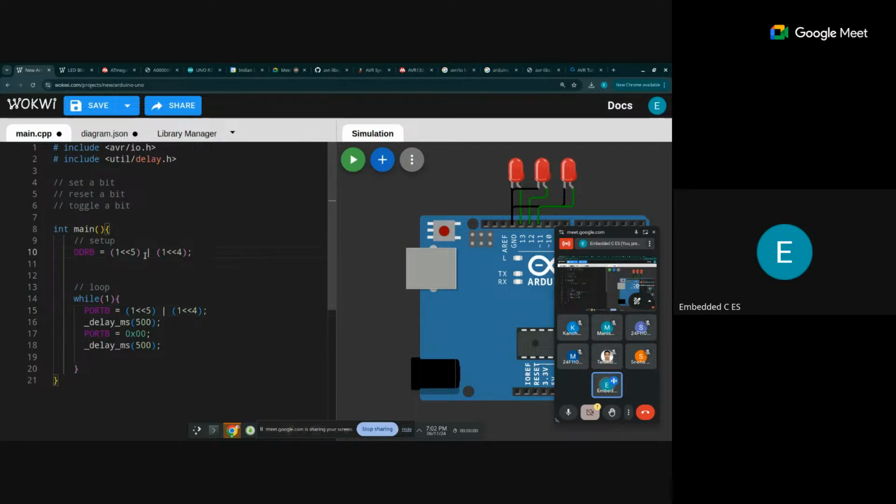Now in our setup we also have to enable this one, which is PB3. So that I can set it like this. So I can select this, right? And one more thing, this AVR library provides a shorthand for doing something like this. So this looks kind of big. So they provide another macro which is defined just like this.